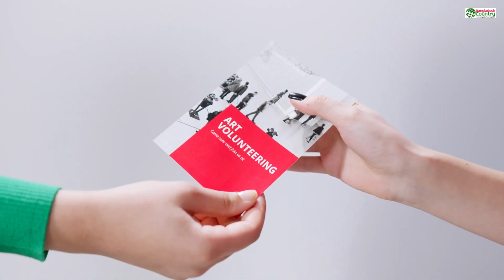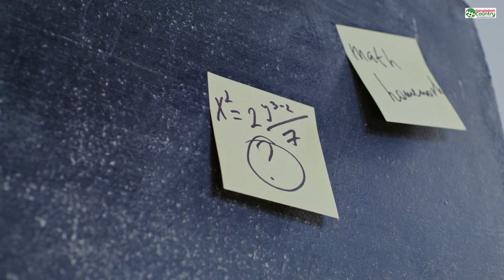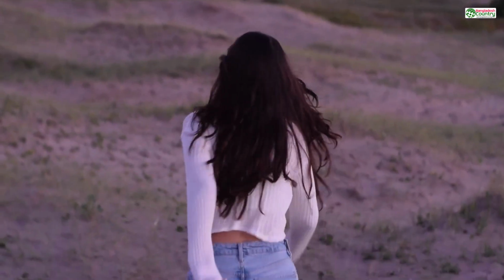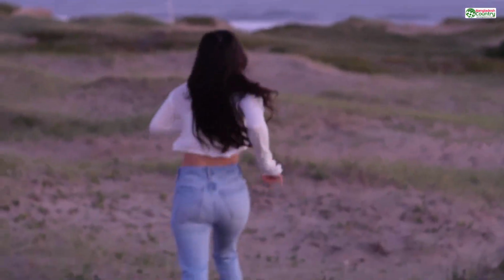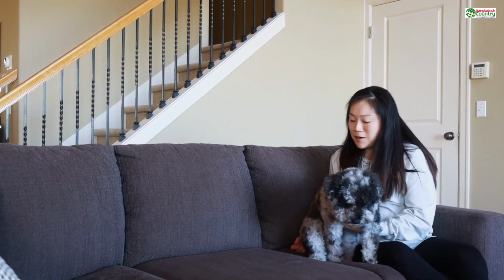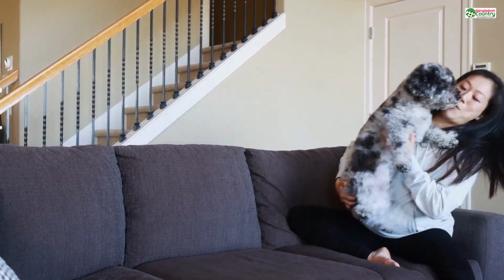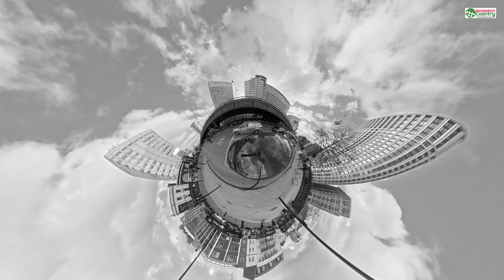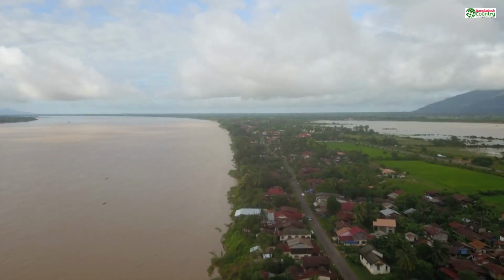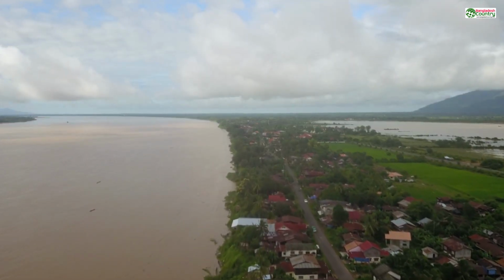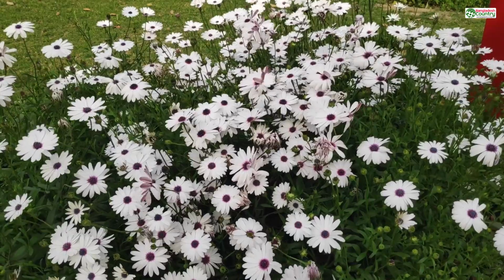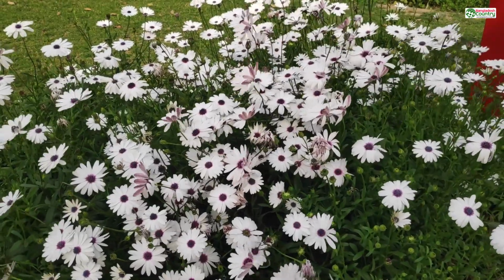The fix is simple math. There are 25.4 millimeters in an inch. So, you go back into your software, select your object, and scale it up by a factor of 25.4. Your 4-unit object is now a 101.6 unit object. Now apply that transform, export it with a scale of 1.0, and when you upload it, the service will read it as 101.6 millimeters, which is exactly 4 inches. Problem solved.